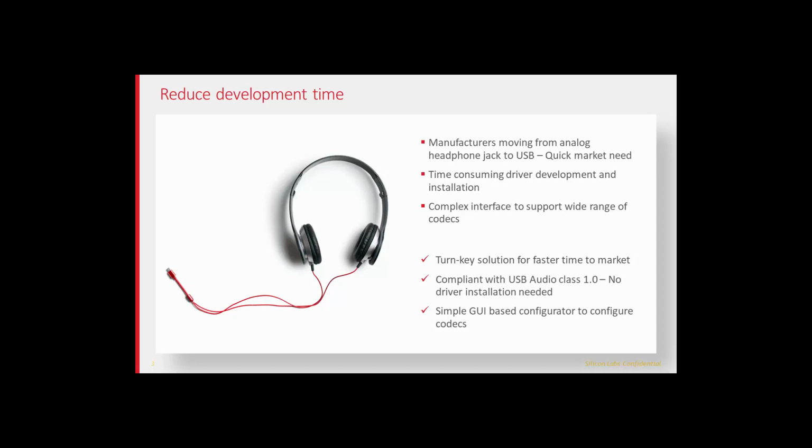And finally, with the 2615, we're offering ways for the customer to differentiate their audio accessories through a number of features with GPIO control and a sophisticated interface between the 2615 and the USB host that enables host applications to communicate with the embedded side through UART and I2C interfaces.